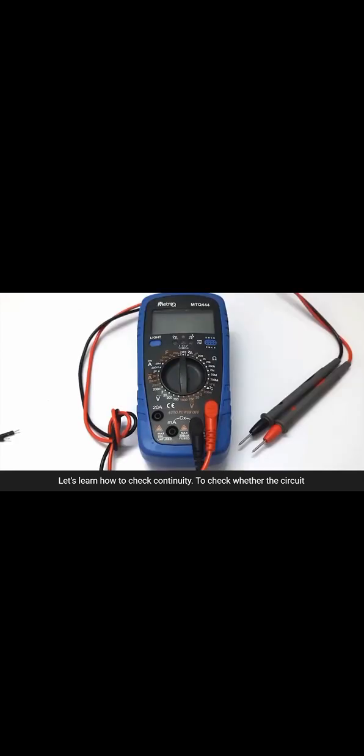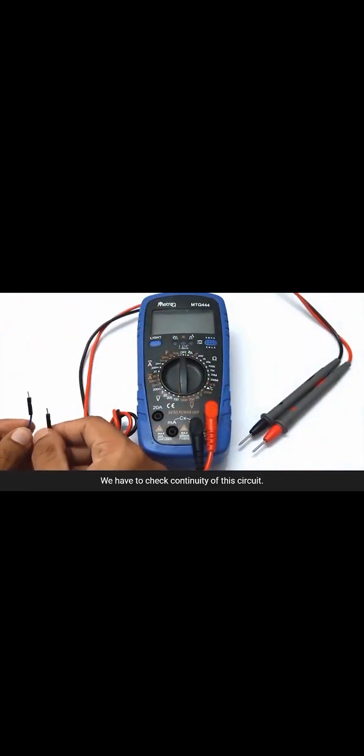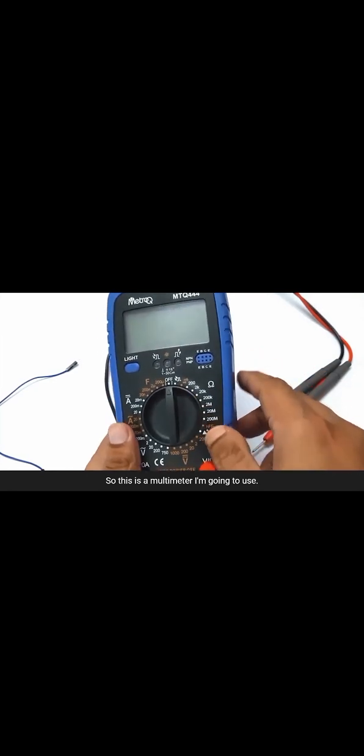To check whether a circuit is open or closed, let's check the continuity of any circuit. To check whether this wire is continuous throughout the line, we have to check continuity of this circuit. So this is the multimeter I'm going to use. You can see a buzzer sound here. We have to shift our knob to the buzzer sound like this.